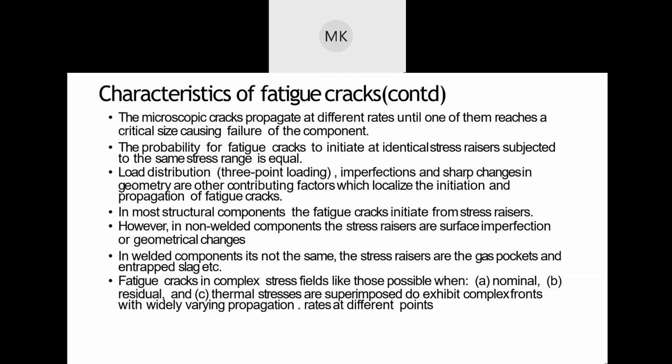Because every end of every grain boundary is basically a door that you have to break out of and go to the next grain. So basically, think of cracks being a SWAT policeman that they have to break into all the rooms every time they hit a deadline. Every time they hit a door, they have to break that open and go to another one. So they have to apply a higher stress. So you have stress raisers at every point, slowing down the rate at which the crack is growing. So all these things take a long period of time to happen.